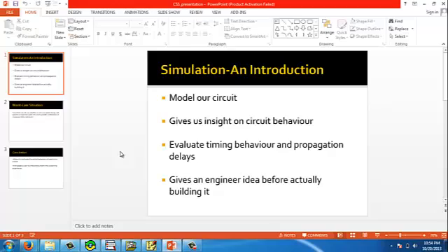delay tolerances. These component propagation delays are generally obtained from manufacturer specification sheets for the components we have used in our design. However, in cases where some of the parameters are unspecified, PSpice can establish the missing values by extrapolation, that is calculating values outside the range of known values.